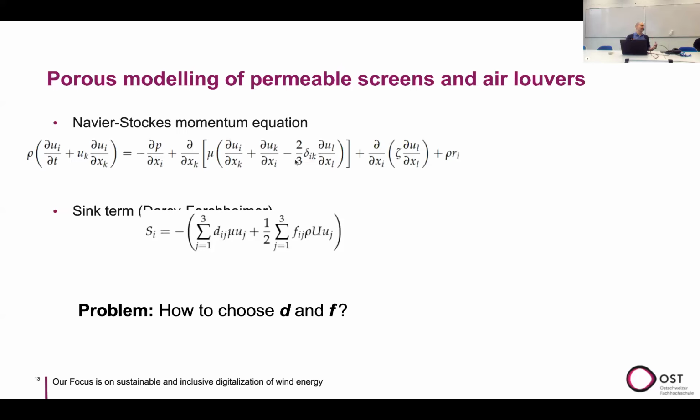Viscosity, at least in air, on a big scale, is not that important, so we can almost disregard it. So we can disregard this huge term and the diagonal, the Darcy matrix, this one. And also this one, because this one is viscosity. So we are basically left with just the inertial coefficients, the pressure, and this is the part of the substantial derivative, the material derivative.